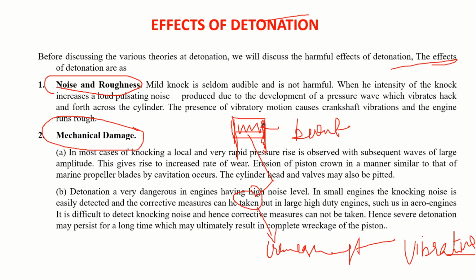These carbon deposits later start acting as spark plugs. That means in the next cycle, before the spark is passed, this may ignite the air fuel charge.